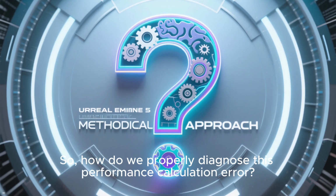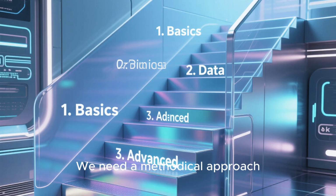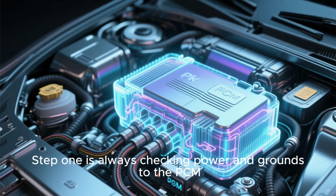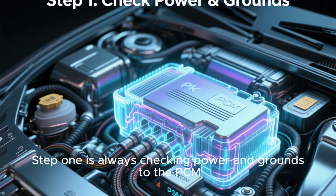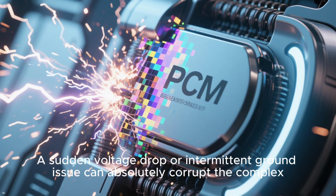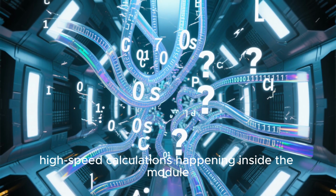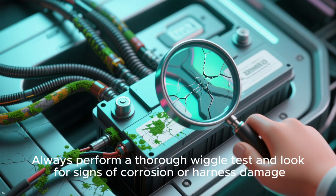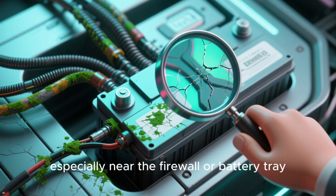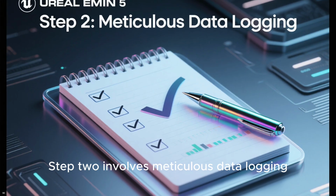So, how do we properly diagnose this performance calculation error? We need a methodical approach, starting with the basics and moving to advanced diagnostics. Step 1 is always checking power and grounds to the PCM. A sudden voltage drop or intermittent ground issue can absolutely corrupt the complex, high-speed calculations happening inside the module. Always perform a thorough wiggle test and look for signs of corrosion or harness damage, especially near the firewall or battery tray. Step 2 involves meticulous data logging.